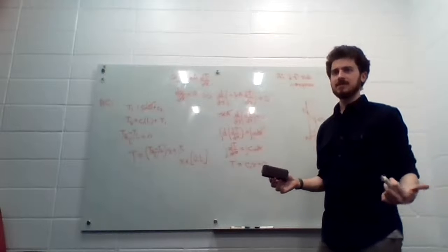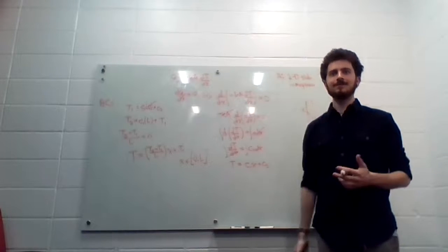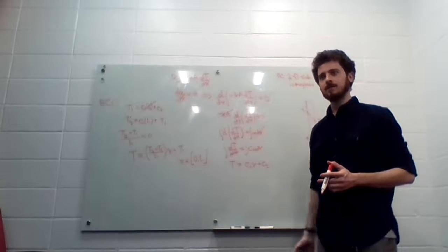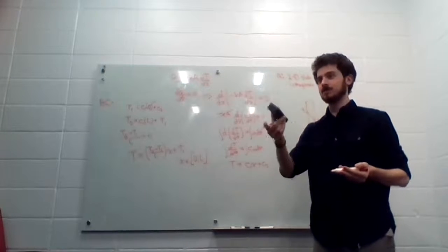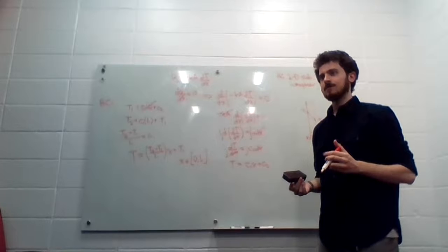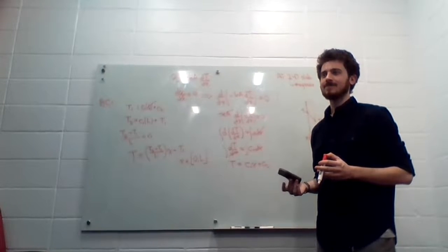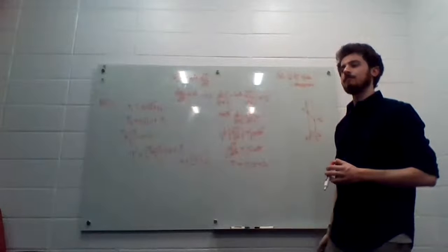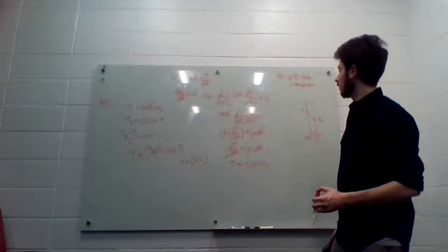Let's just remind ourselves of the assumptions. What are our assumptions? Homogeneous material. What else? Infinite wall, which is basically another way of saying one-dimensional heat transfer. 1D slab, we just said that one. Linear temperature difference. We arrived at linear temperature difference based on these other things. But another important one is no internal heat generation. I think that's the last one.